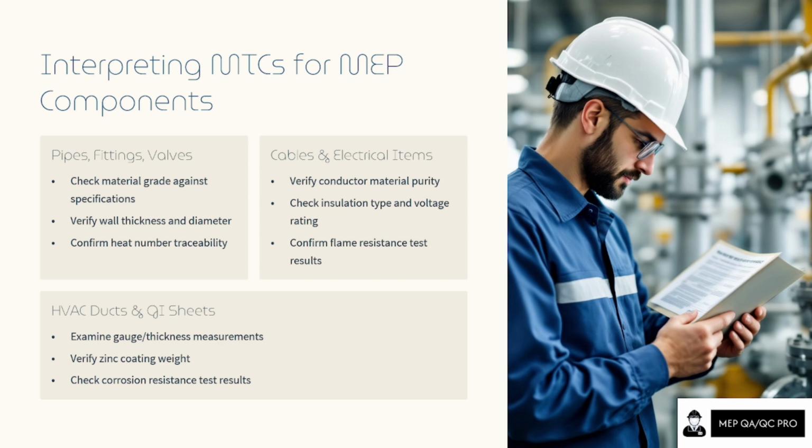Check also whether any corrosion is there or not. All of this you can get through the material test certificate, and you have to cross check it by your own routine inspection while checking any material arriving at site.